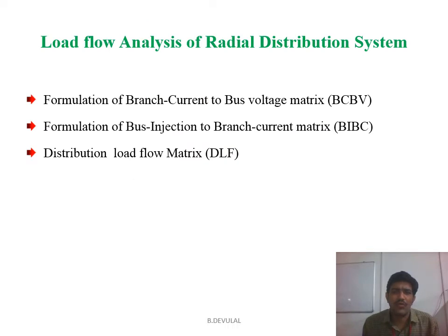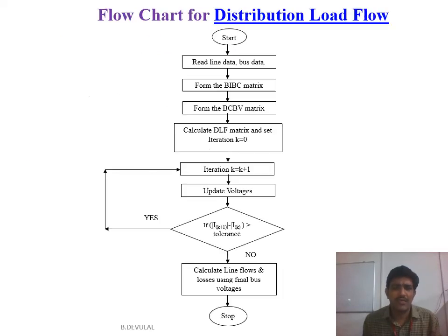Then I apply the load flow analysis for the radial distribution system by forming the branch current to bus voltage matrix and the bus injection to branch current matrix, and the distribution load flow analysis. These three methods I have to use, and I have implemented one algorithm.